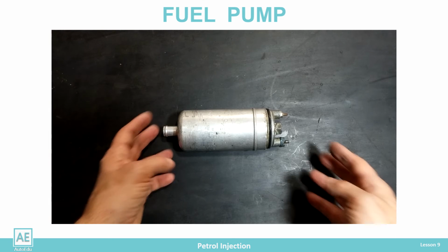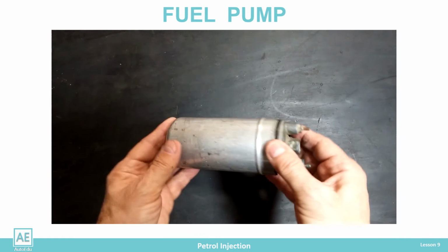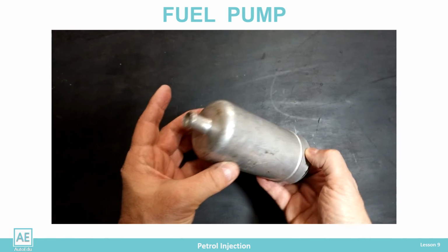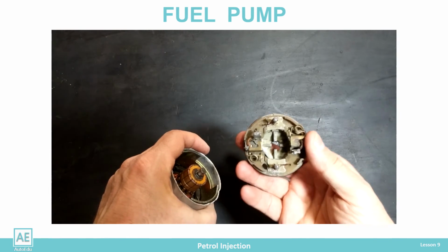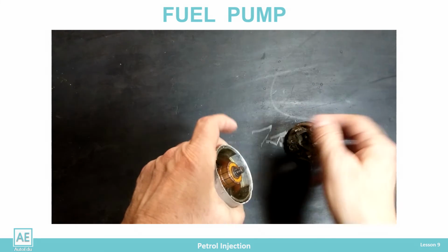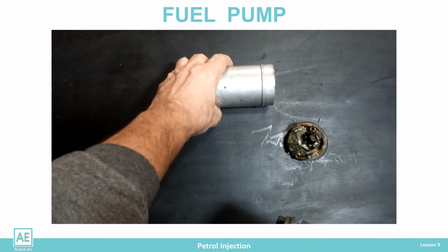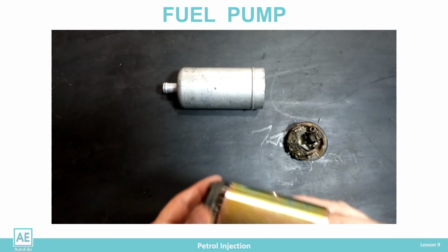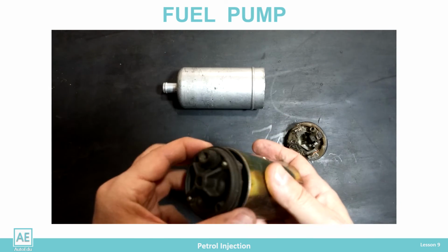The electrical connections on the pump must be clean without dirt, corrosion, and burns, with a good connection to the outlet. If there is a transient resistance, the pump receives a lower voltage and cannot deliver enough fuel to start the engine at startup. The voltage difference between the accumulator and the pump connections must not exceed 1 volt.